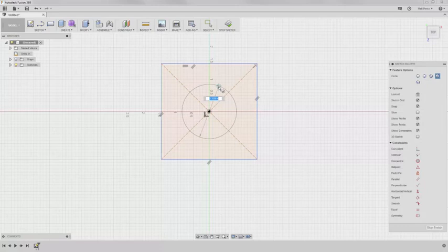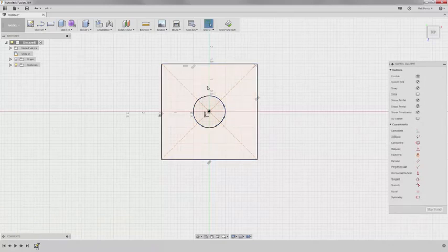on in the sketch. At any point in time, you can hold the Control key on the keyboard, and this will allow you to override the snaps so we're no longer snapping to the grid. For now, just drag along the vertical axis until we're at a 1 inch dimension and then left click to create the circle. To stop the tool, press Escape on the keyboard.